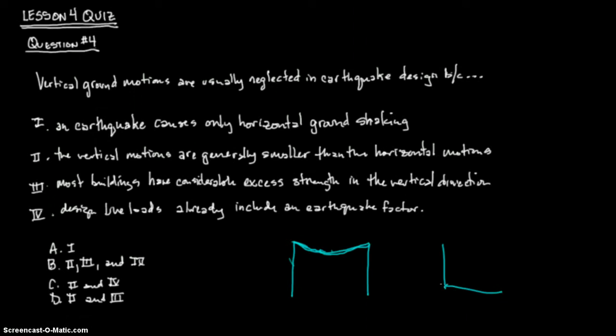Once again, you have the elastic curve that goes up like this and then goes over like that. This is stress and strain. Sorry, that's not the best. If you put the stress up to this point, it will go back down. But if you stress it past this point, then when you release that stress, it ends up permanently deformed this much. That's your permanent deformation. This may have permanently deformed because of the overstress from the earthquake, but it did not see its ultimate stress, and therefore its breaking point. So you're good. I hope that made sense.